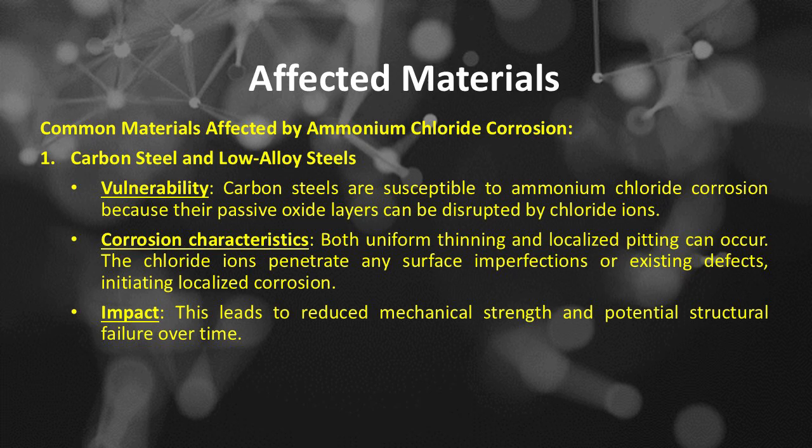The chloride ions penetrate any surface imperfections or existing defects, initiating localized corrosion. The impact of ammonium chloride corrosion on carbon steel and low alloy steels is that this leads to reduced mechanical strength and potential structural failure over time.